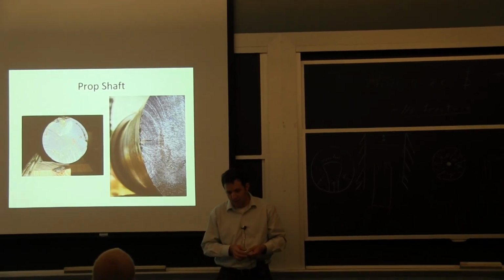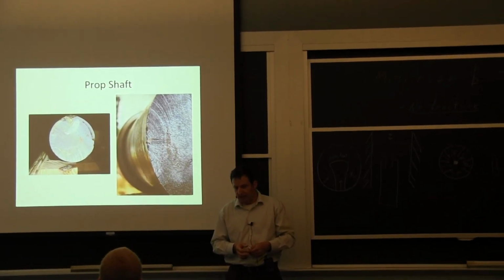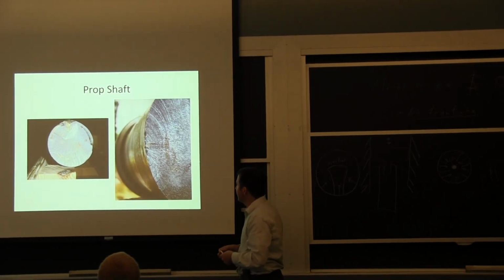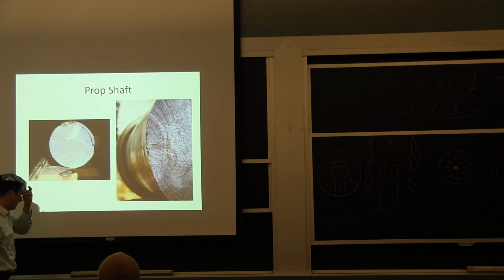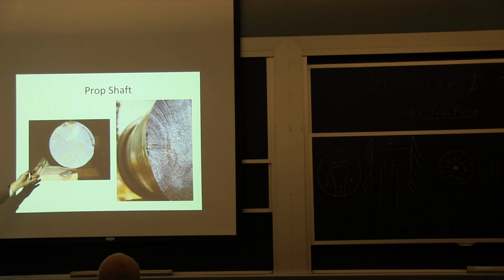That's another example. I think based on what I just said, you could take, this is about 8 inches in diameter. It was a propeller for a big boat, a speedboat, where only half of the prop is in the water. So if I'm looking back here, this is coming out of the hole. It's a straight shaft, and only half of it is in the water. So each time I turn, I have a lot of bending moment in that shaft.